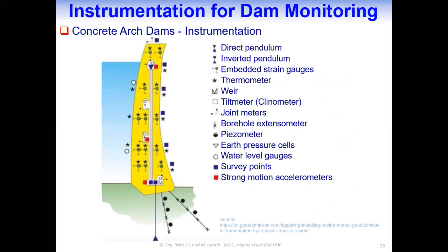So, in this case, a similar set of instrumentation to that used for the gravity dams could be employed for the arch dams also. However, due to the solid foundation conditions that are usually associated with concrete arch dams, we could ignore the earth pressure cells. That's optional